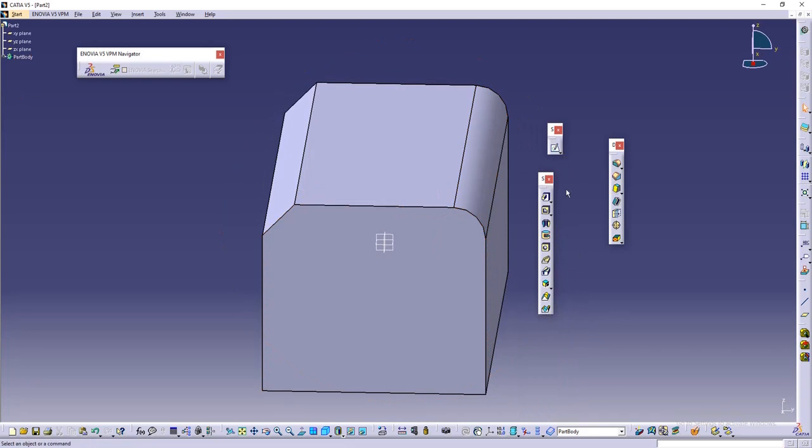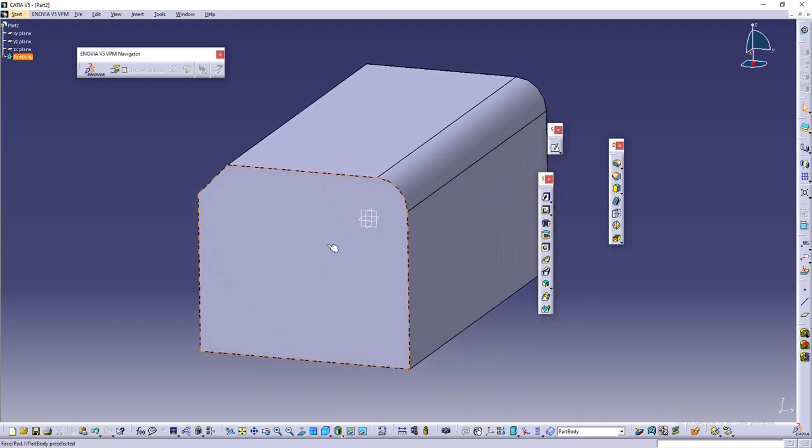So only with the use of pad or a cut. Now we will see the pocket here. They don't use the word cut option in CATIA. They directly say the pocket, how to create a pocket. It is a separate tool, right? So same thing, what you have to do here, again we have to sketch something. So we'll go to the sketch option.